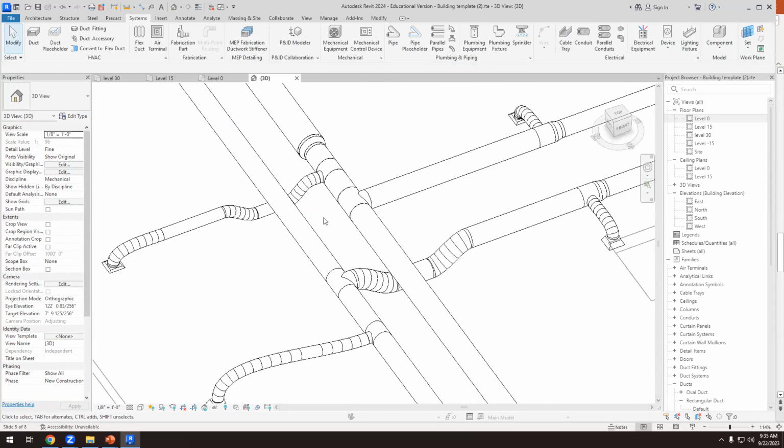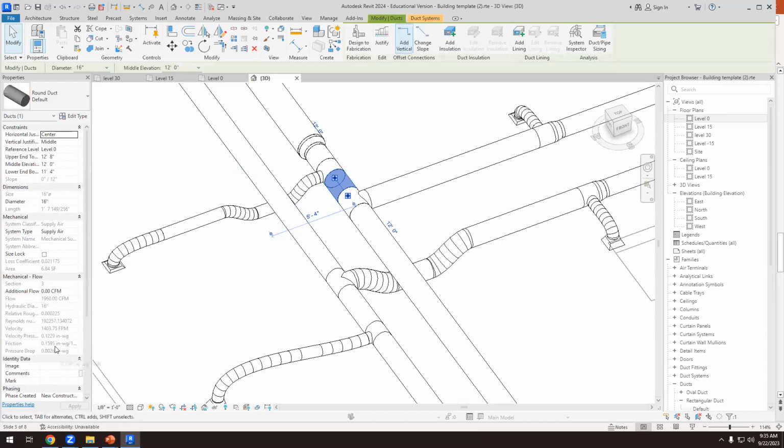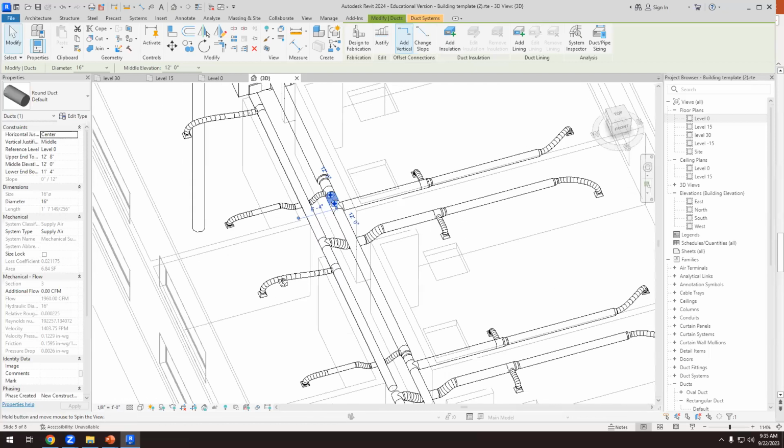Isn't your airflow too much in between that reduction by T on the flex stuff? The next one up. The velocity is 1400. Yeah, it's too much. But if you just delete all that T and stuff and draw your 20-inch duct and connect it to that T down there. Yes, that's another option. And you won't have all those connections. You can do it, okay? But yeah, what I did, I connected the... Yeah, you did it. Okay, so that's fine. Yeah, it can be better. So I like your solution better than mine, but I won't do it again.